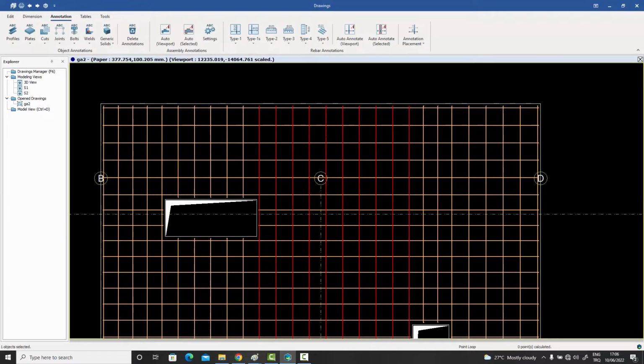The first point you want to select is where you want the bar to be placed. Since it's a free point, you don't necessarily have to snap to any one of the snappable points. If you want to snap to a free point, let's say over here, then you need to press the Alt key and click at that point. The moment you do that, the range is decided for you, not the location of the bar. So this is where it'll put the range, and then you can place the bar anywhere you want. Let's say you want to put it over here, so you press the Alt key again and you click over there.